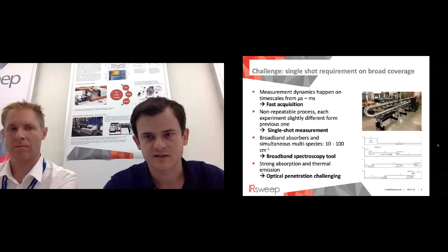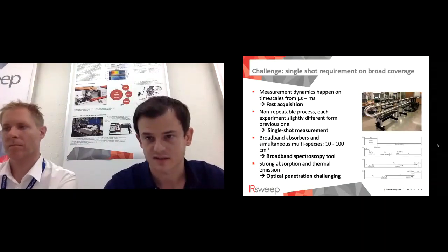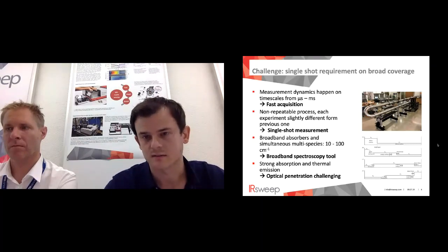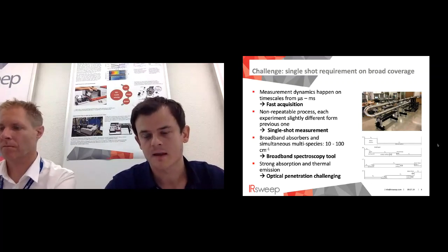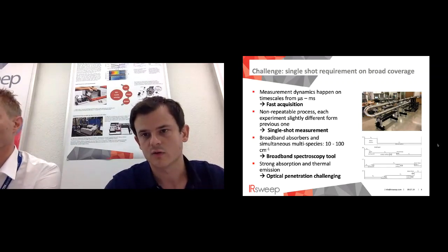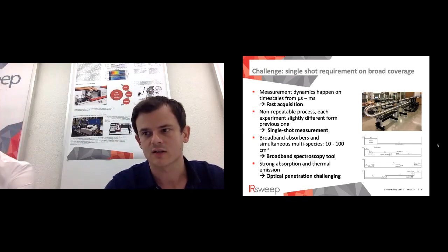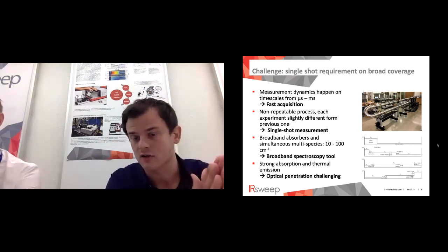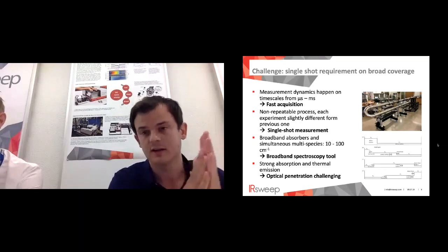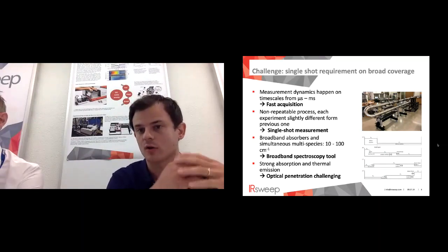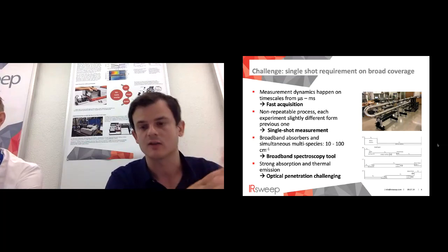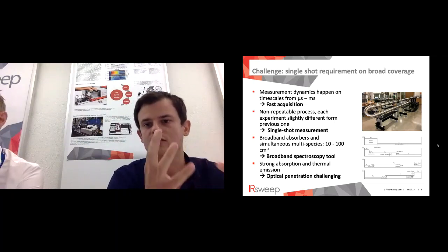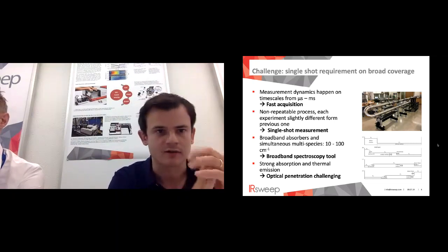So why is it relevant to offer new methods for combustion diagnostics? What you see here on the right is a picture of a so-called shock tube. It's a machine that is used to simulate a combustion. You load the fuel and the mixture that you want in there, and then you run a shock wave down the tube until you hit the end wall, and then you generate the conditions through the shock wave that you want, to do a combustion or a pyrolysis or whatever it is you want to do, and then you want to study this. Drivers are, for example, clean combustion or understanding kinetics.